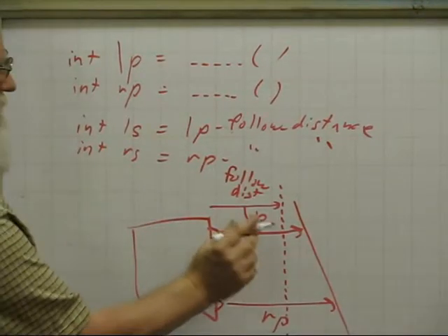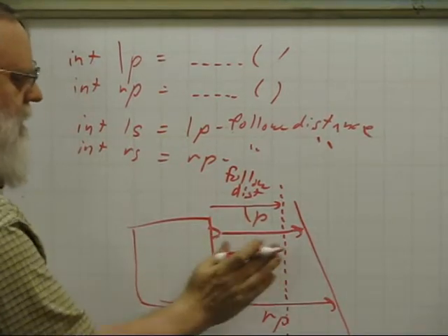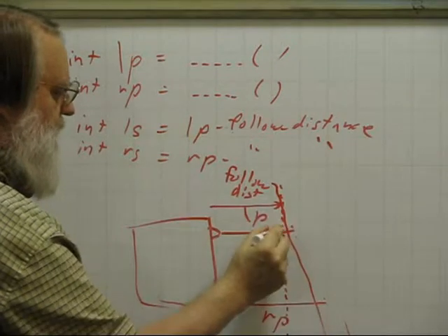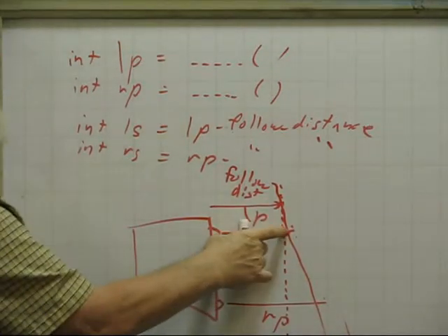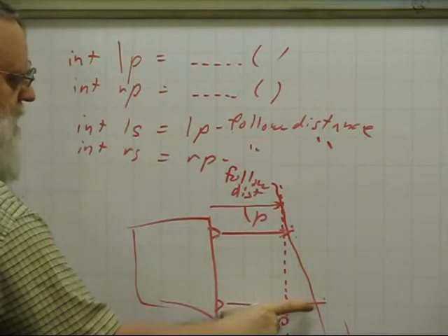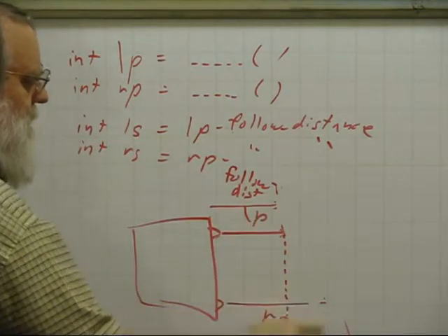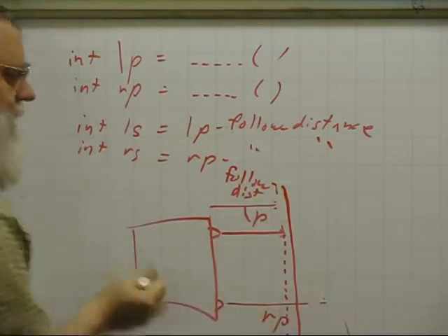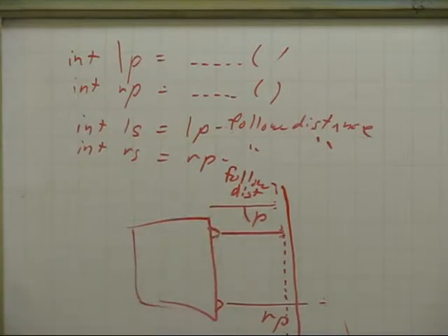What that means is it's going to go forward. And then as it's moving forward, eventually, this one will be at the same distance. Your speed will shrink to 0, and that motor will stop. This one isn't there yet, so it keeps going forward, and it actually turns this way, but I'm going to draw it this way because I'm lazy. It will turn into it until both of the wheels are basically the same distance from your platform.